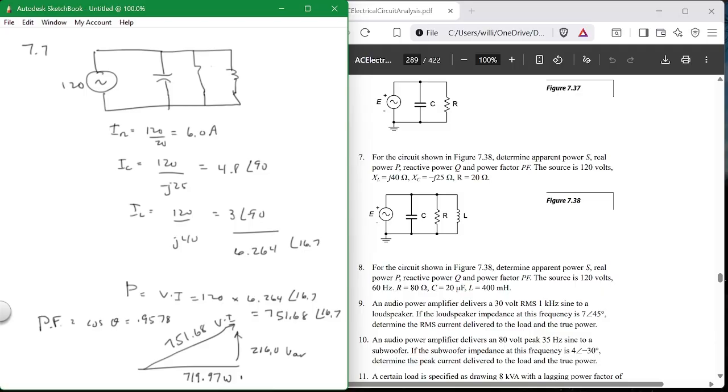Now, is anybody going to beat you up with this power factor? No. Anything above 0.90 is usually okay, it's acceptable. Some people say 0.95, and you're 0.957, so you're okay. But they're going to have a rule of thumb for your factory or for your plant or wherever you're at. They're going to say, what is our power factor and what do we need it to be? And they get a bill from Toledo Edison or whatever, and they tell you what your power factor is.